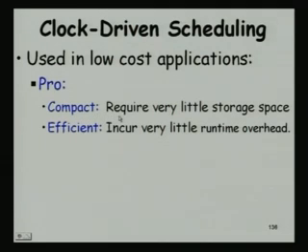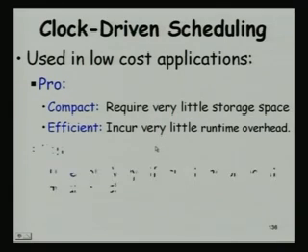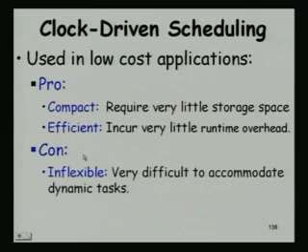The algorithm is extremely simple, nothing much actually, based on the clock interrupt. Look at the table, select the next task. These are efficient, very little computation needs to be done each time the scheduler runs. But if we have to talk about disadvantages, I think some of you had already mentioned today that these cannot handle tasks that arrive dynamically.